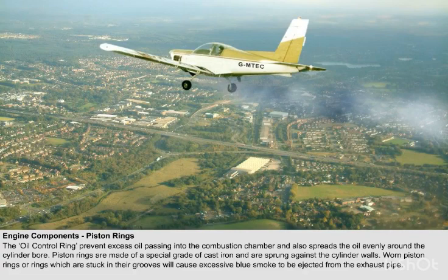Piston rings which are either worn or stuck in their grooves will cause excessive blue smoke, which is burnt oil, to be ejected from the exhaust pipe.